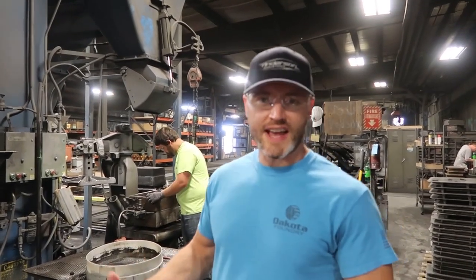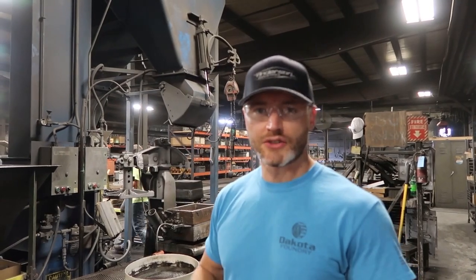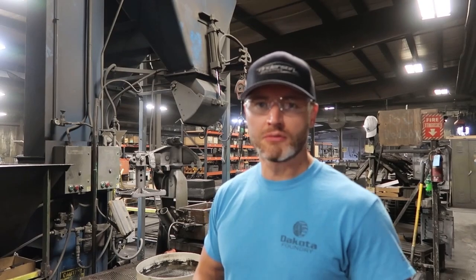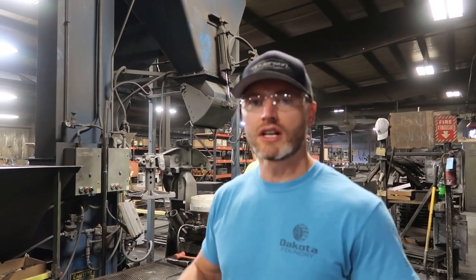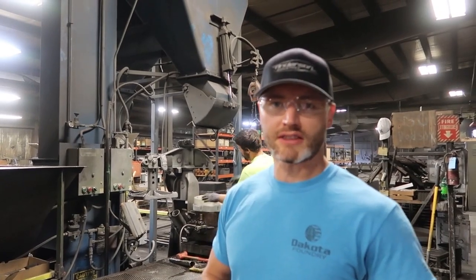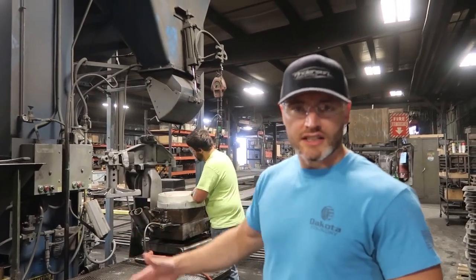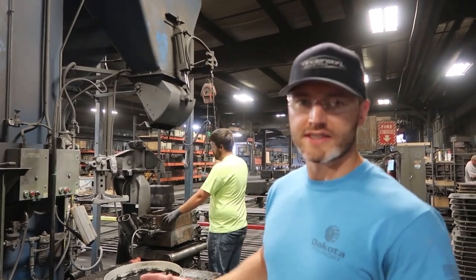Here we're in our green sand molding area, so we have two squeezers for doing green sand match plates, so we can do low volume, primarily low volume, one-off stuff. We can use either a match plate squeezer or loose patterns, where we can make the molds here. So green sand molding, castings up to about 75 pounds max on this line.